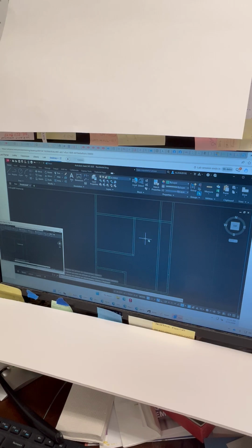All right, now I'll select this lower horizontal line here, the lower one from the wall that divides the bedroom from the bathroom and closet area. I'll move my mouse below to the south of that line and I'm going to type in the distance 4'2" and hit enter. Now, this is the tricky part. I want everybody to select this line, but you're not going to click below it.